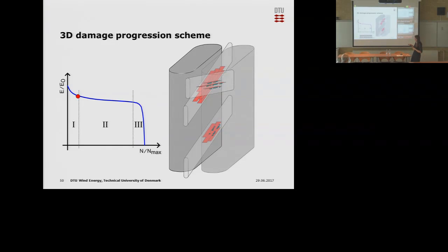Then after a little bit more cycling, the off-axis cracks are growing and more are appearing, and probably some more associated fiber fractures are occurring. With further cycling, we get close to saturation of the off-axis cracks, and the fiber fractures start progressing into the unidirectional bundle in the different regions. This region is probably going to be larger than this region down here.